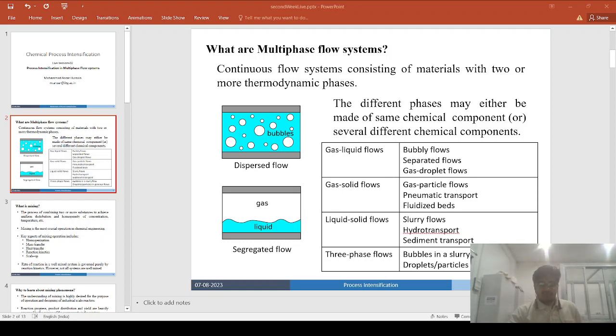Now, in such silicon lithography fabricated microreactor devices, the standard catalyst particles, 50 to 75 micrometer in diameter, are retained in the silicon channel by an integrated microfabricated filter unit.